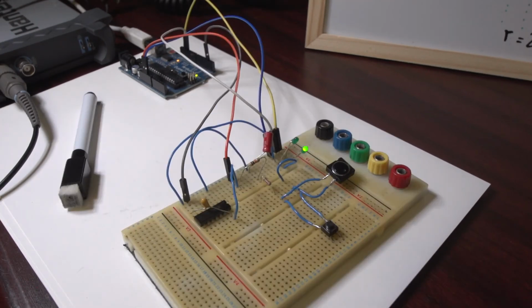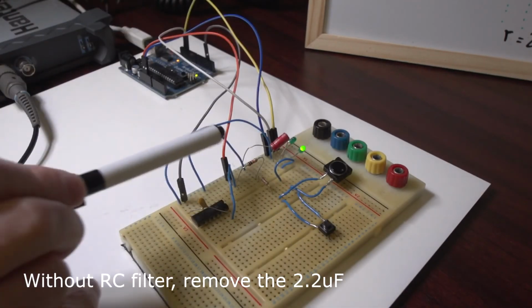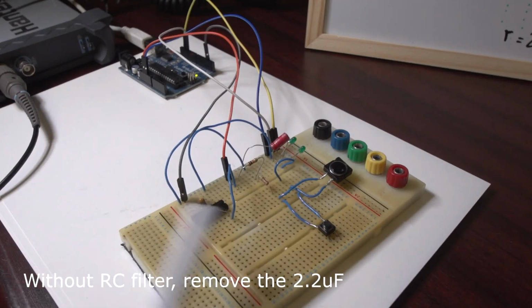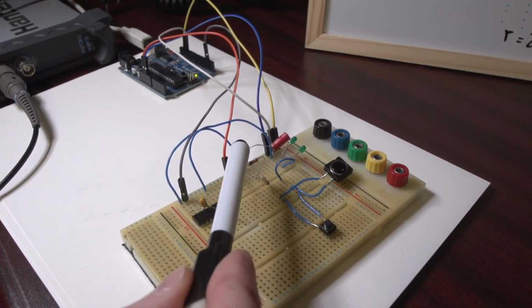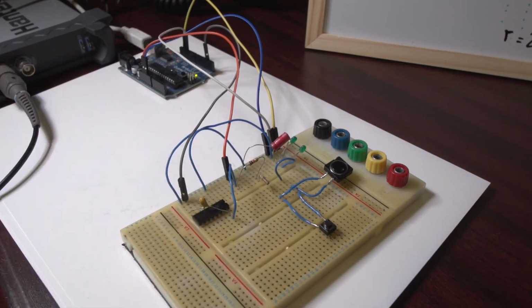Just to demonstrate the problem further, if we didn't have the RC time constant filter in there, I can demonstrate that and show you what happens if you don't have this circuit. So I can remove the 2.2 microfarad capacitor. I've just pulled out one of the legs of it there, so it's now not connected. So this is the circuit. We've still got the Schmitt in here for the fast rise time, but now we're going to have contact bounce not filtered by the capacitor. So we're going to send contact bounce to the chip, and this is what happens.